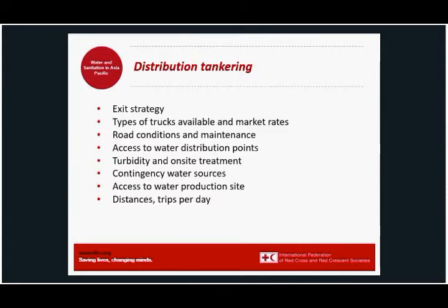Tankering operations, however, are expensive and relatively time-consuming to administer. So it is necessary to consider the exit strategy from the outset. Remember, tankering is much more efficient if water can be offloaded to storage tanks rather than allowing people to collect their water directly from the tanker.